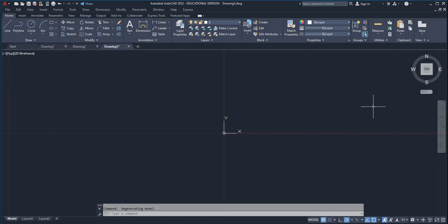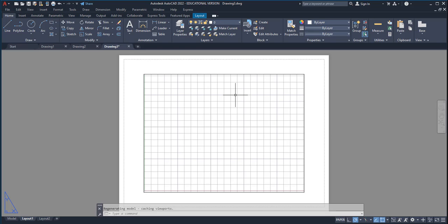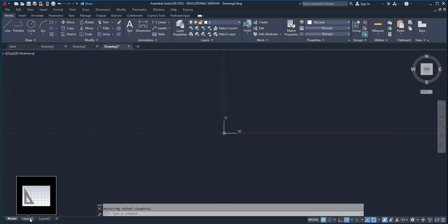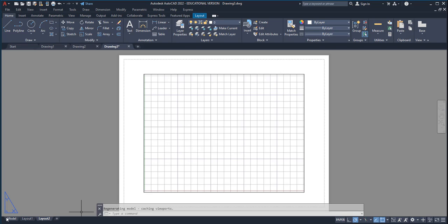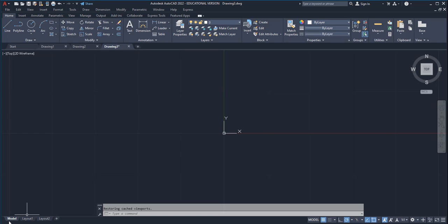Okay, so the drawing area, UCS, and then you have the layout. Layout is right here where it says model, layout 1, layout 2. We'll get to that when we start to put together a set of drawings, but what we're going to draw in is always the model space, not the layout. If you do that, it makes it look like a preview of a paper, right? Basically this is a little window that peeks into the model space. So we'll come across this when we get to the lesson on that. But for now, please keep it in the model tab.